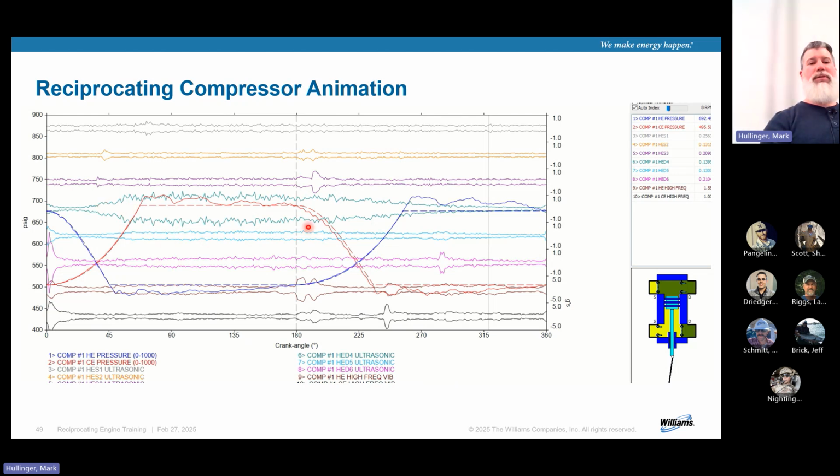Before I move to the next slide, what's this? Valve, yeah. Is it good or bad? It's not great. Yeah, that's a good way of putting it. We say good or bad, but a lot of times there's stuff in the middle, right? Compared to the other ones, what's it doing? Yeah, it's leaking. Good point. I might have one of those pictures. So is that a suction or discharge valve? Yep, yeah, so you can look right there and cheat, or you can count down. Or if you know where it's leaking, you can say that's probably a discharge valve, but you're exactly right, discharge valve head end, okay?